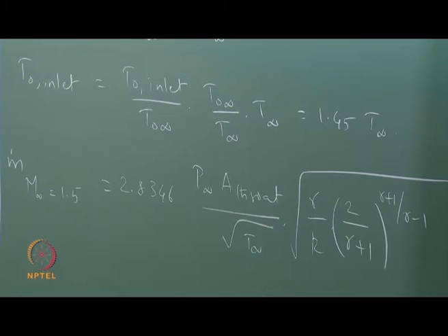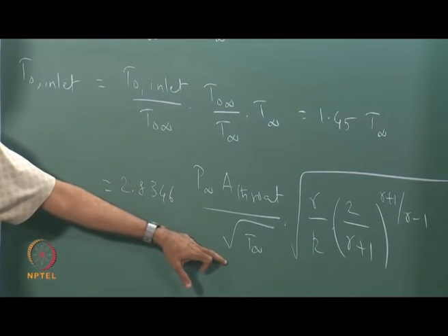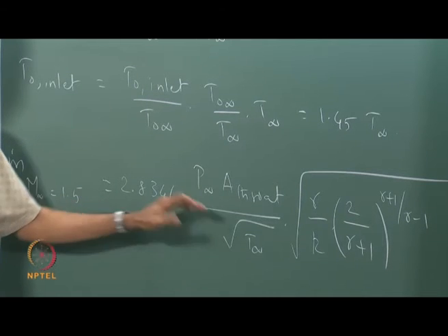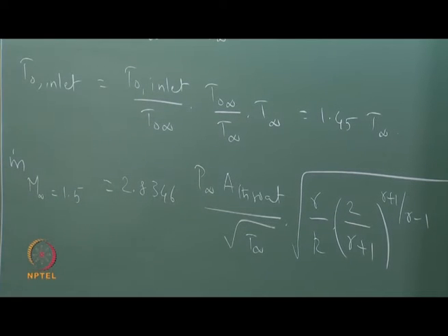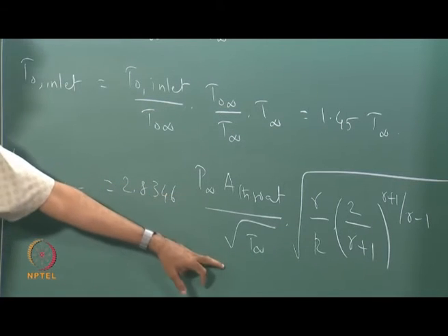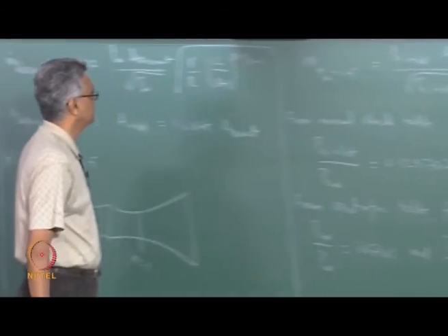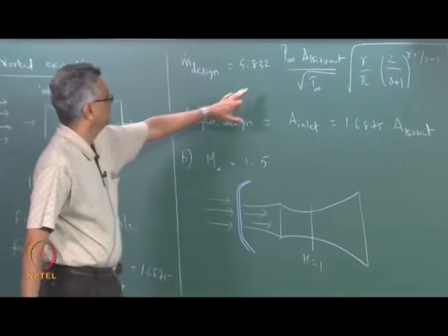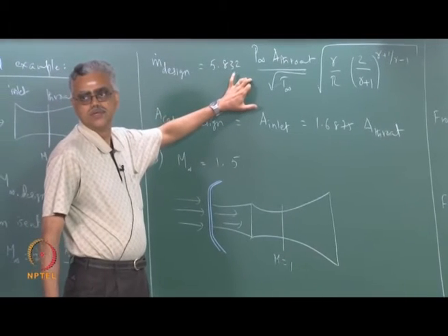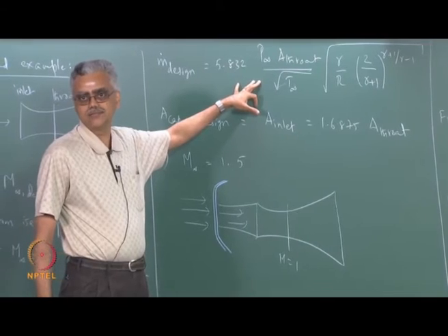It now becomes clear why we wrote everything in terms of the free stream static quantities, because although the Mach number has reduced, the free stream static pressure and static temperature remain the same. We are only looking at a reduced speed for the intake, which is why we wrote everything in terms of P infinity or static conditions. So, we are assuming that static conditions remain the same; I have only reduced the speed of the intake.